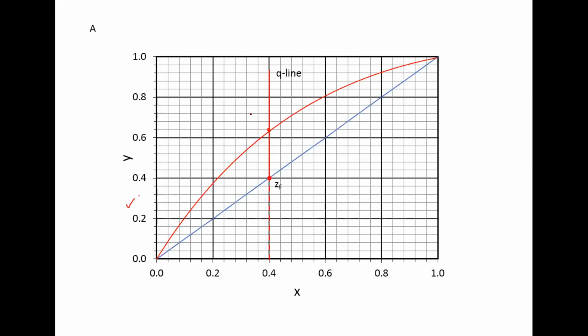Yes, ma'am. Okay. And then to get the reflux minimum, the reflux minimum is where the equilibrium line and the Q line intersect with one another. And then you start to intersect that point to the XD.